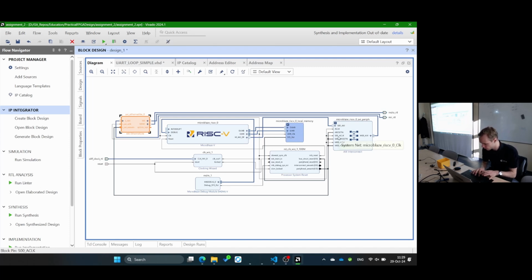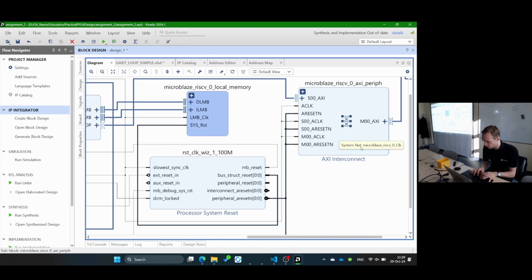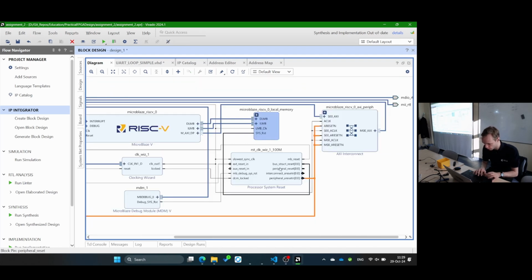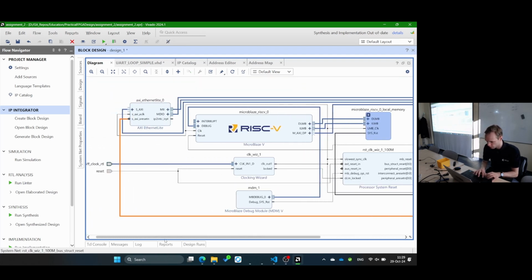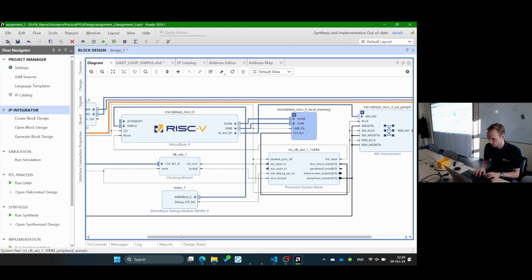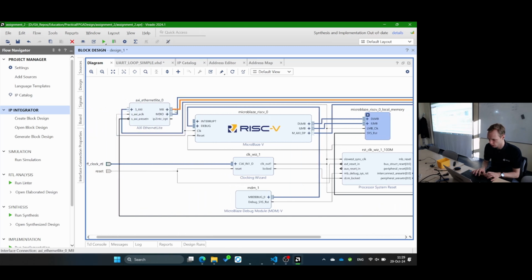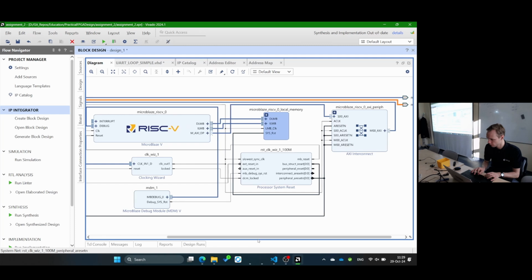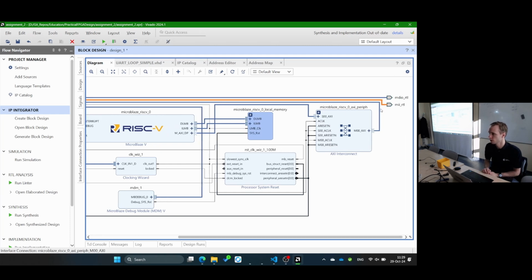So essentially I have a master, which will go to my Ethernet, have a reset, but also here I will get the data from a slave. The Ethernet is obviously a slave in this case. Get the data out into my Ethernet, and I will also get in the other direction the data back in here into my Ethernet ports on my hardware layer, into my pins. And this way I have just now written a RISC-V processor with Ethernet.